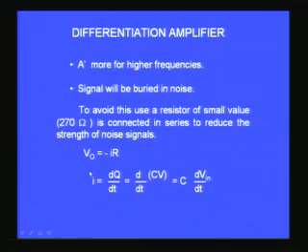Now we also know from fundamentals that I is the rate of flow of charges, I is equal to dq by dt, the rate of charge flowing, and that is equal to d by dt of Cv, because the Q is associated with the capacitor at the input, and the relationship between Q and the capacitance is Q is equal to Cv, therefore differential of Cv divided by dt. In this, C is a constant, V is the only thing which is the input voltage which is going to vary, and therefore I can take the C out. Therefore this equation, I becomes C into dVin by dt, right. This is the current.